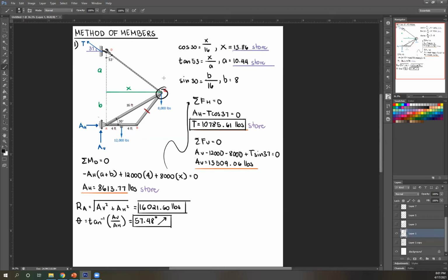Let's look at joint C. Can I use it there? One force we have is tension. So that's obviously an actual force or an actual member because tension is just along your wire at all times. How about this? Member AC, there's no force acting on its length, right? Therefore, that's a two-force member. Same with BC, it's a two-force member. So I can apply method of joints at C. So you can try solving for this using method of joints at C, or another method would be using method of sections. But we're gonna use this as your cutting plane.